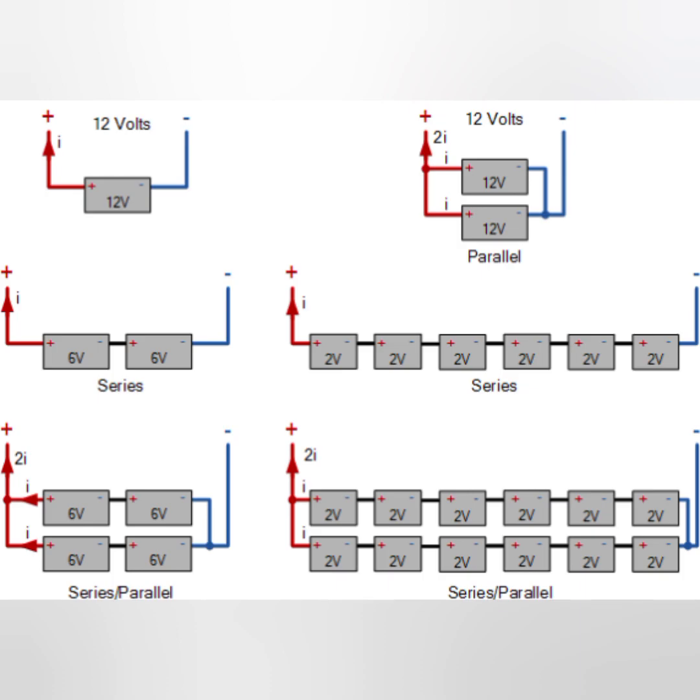First, series: two 6 volt batteries are connected in series, which means automatically it will form 12 volt, because the voltage gets increased and the ampere hour will be constant. In a parallel connection, when we connect two 12 volt batteries in parallel, automatically the voltage of your battery will remain the same, and the ampere hour of your battery will increase.